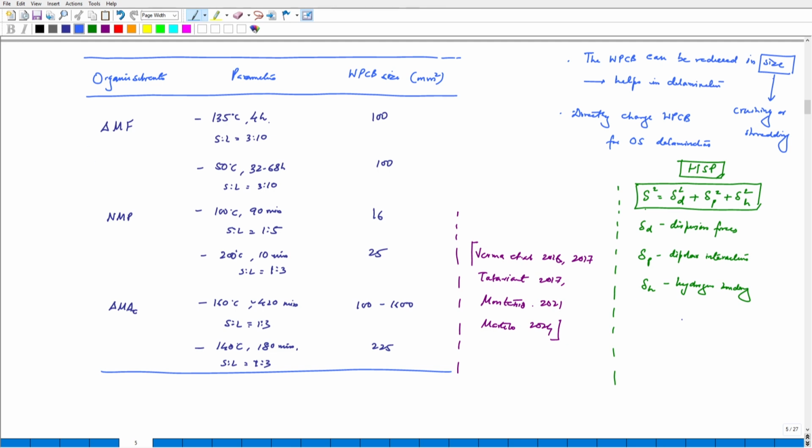So some other routes that are being investigated are, and we are just highlighting them because these are being investigated. These are co-heating swelling, wherein we are just heating the organic solvents while they are having the PCB assembly inside it. So co-heating is basically we have a bath, we have organic solvents, and then we are heating it. It helps us in having that action of heat transfer and the action of organic solvents, and it helps in the removal of the components a lot more quickly.